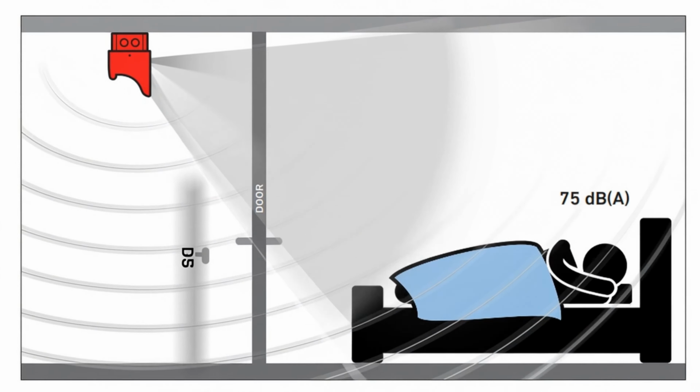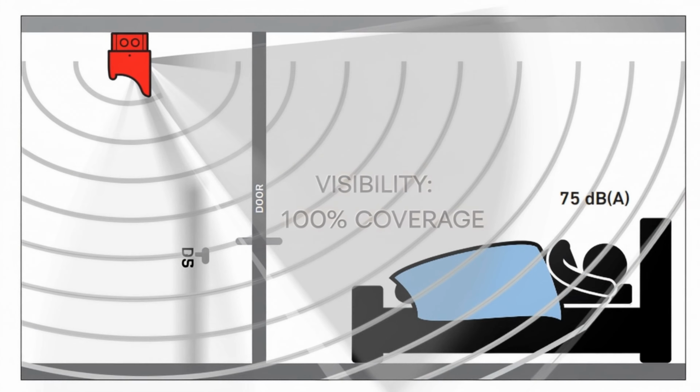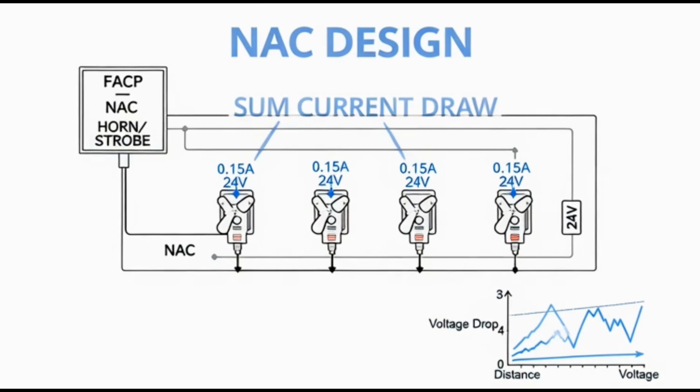The message must be received. Sound must be 15 decibels above average ambient noise. Strobes must be visible from anywhere in the space. Calculate candela ratings carefully.